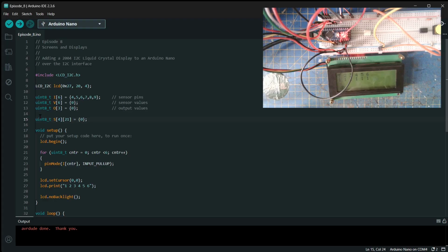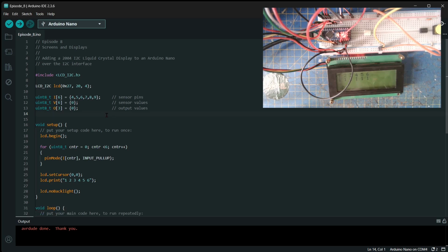Just so you can do that. But you could go in and you can say, I want to write character at position 4 such and such. And then when I output, I want to output all of that. Here, that's not a good idea, because these displays aren't particularly fast. So at the moment I'm writing out single characters, which is quite quick. Writing out them all, it doesn't take long, but it takes a little bit longer.